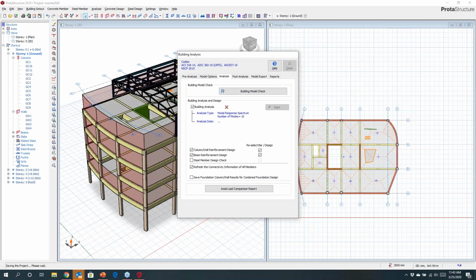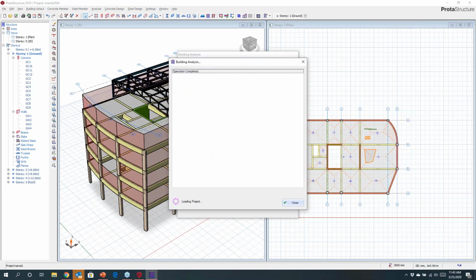Okay, so just give it a second. It's saving away, and then you'll see the analysis kick up, and we will move through and run the analysis. Now, this is a physical model, and what we're doing is we're automatically distributing the loading from the slabs and the beams, so from the slabs to the beams automatically.